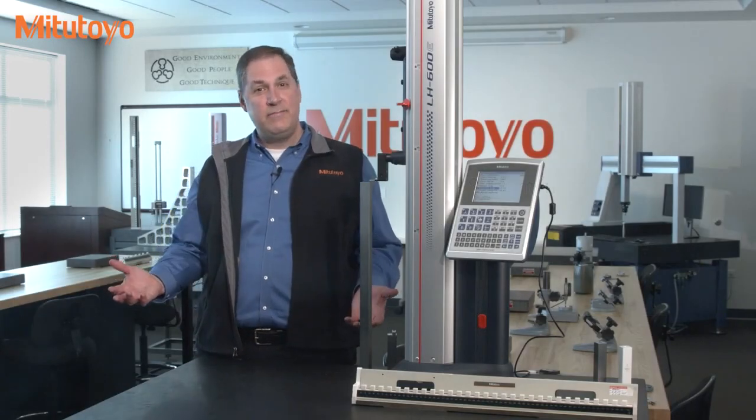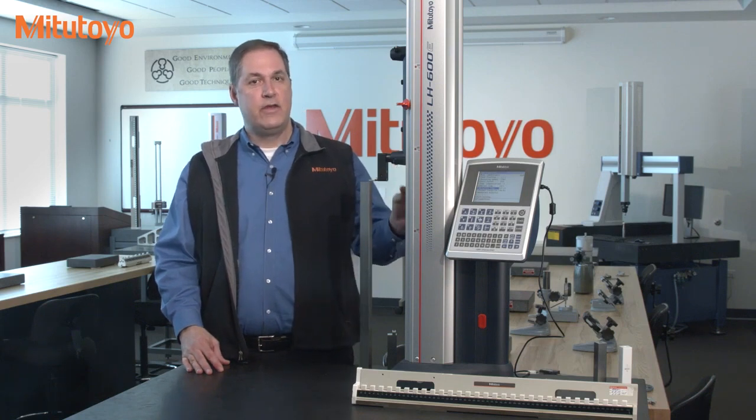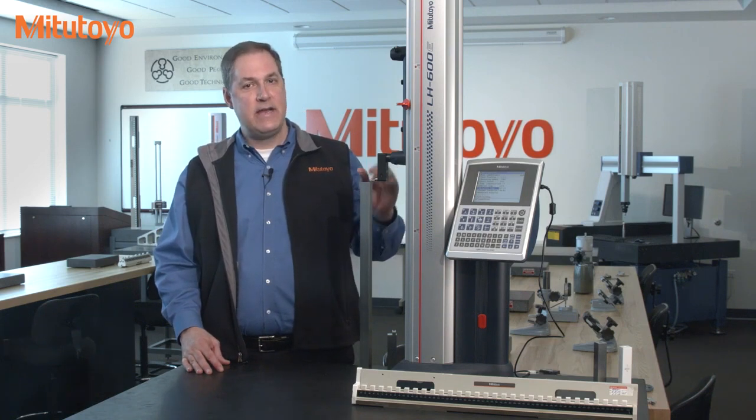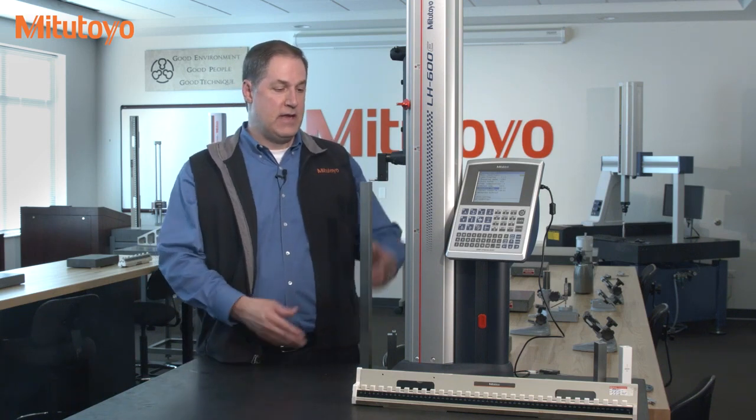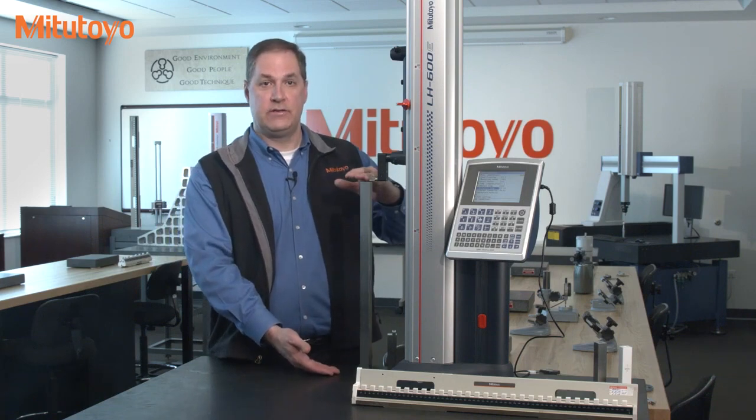So is that a problem? Well, if you look up the accuracy tolerance for this linear height, the 2.7 micron temperature error is about twice the accuracy specification for this unit at this length of 20 inches.